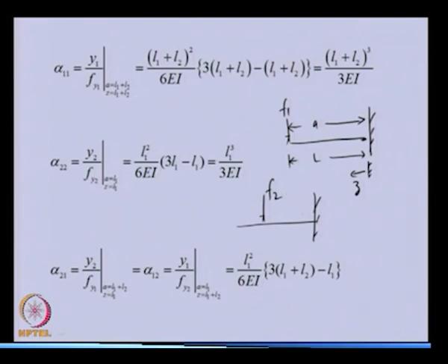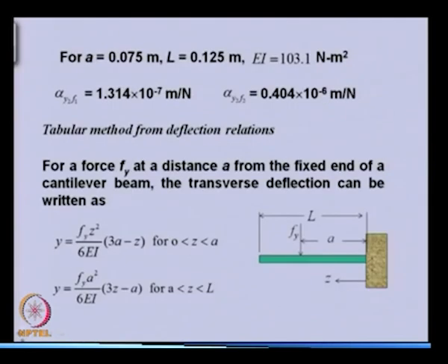So, you can see that basically A distance was this, which is L1, and Z is also at L1, because we want the displacement at the same position where the force is. And so, the same expression which was there earlier will be used. Now, in place of Z, we need to keep L1, and in place of A, we need to keep L2.